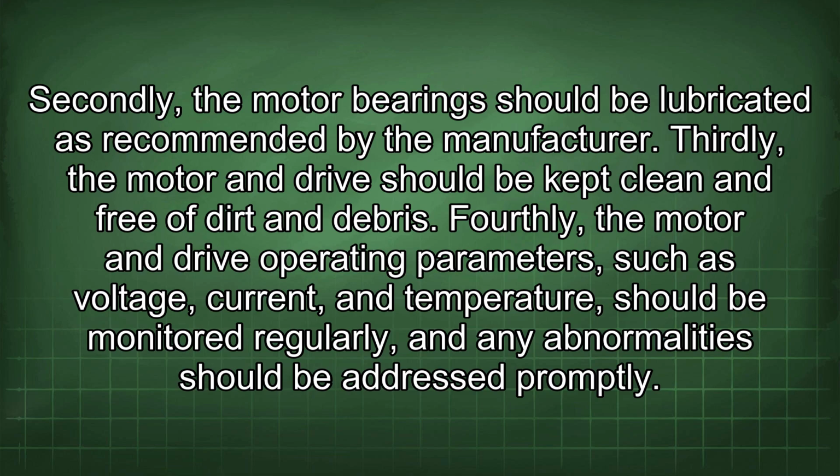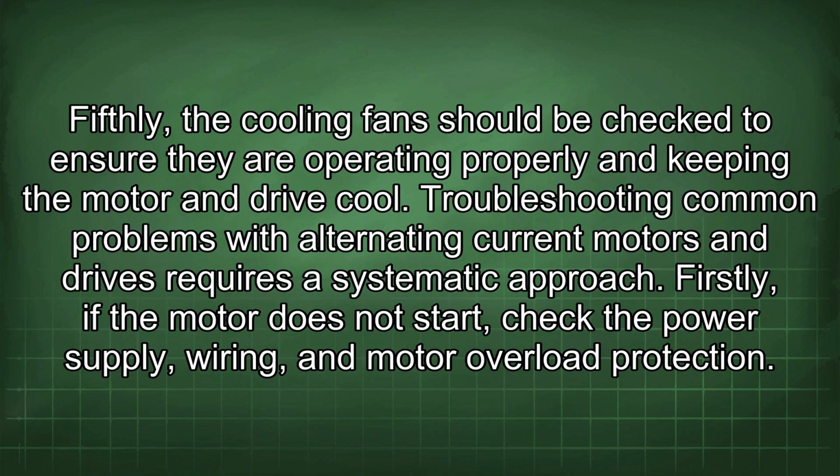Fourthly, the motor and drive operating parameters such as voltage, current, and temperature should be monitored regularly, and any abnormalities should be addressed promptly. Fifthly, the cooling fans should be checked to ensure they are operating properly and keeping the motor and drive cool.